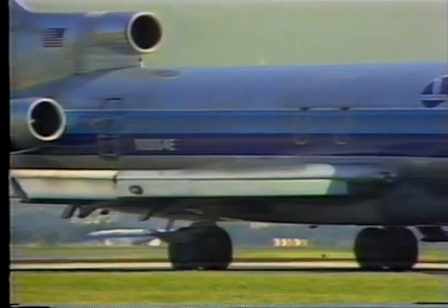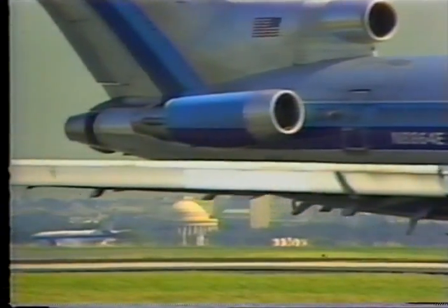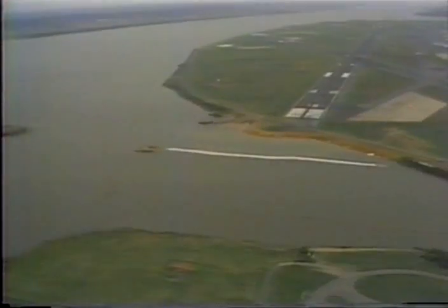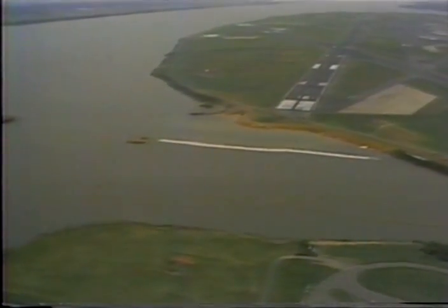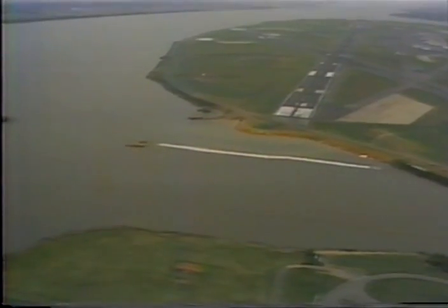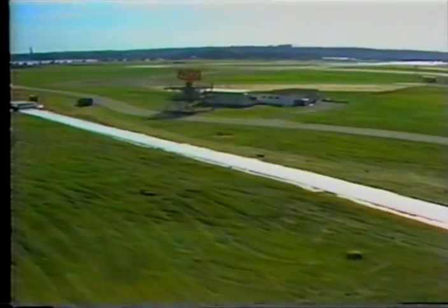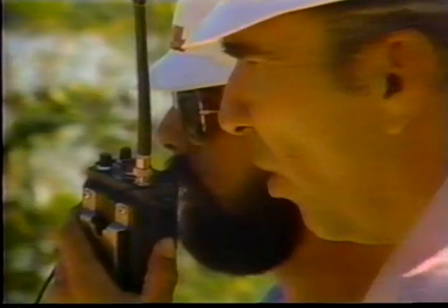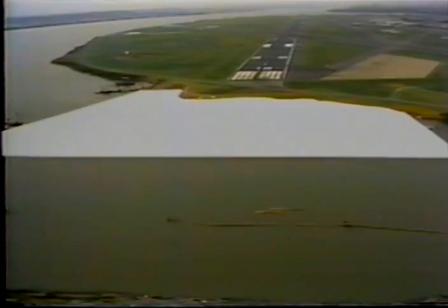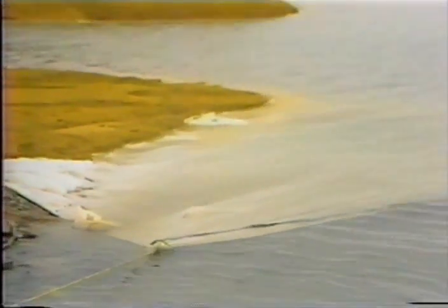In the early 1980s, a new runway extension was created for Washington's National Airport. It was constructed on an embankment section founded on soft marine deposits. For this project, a high-strength geotextile had to be specially manufactured. Once the lengths were seamed together, it covered an area the size of 3 city blocks. The accordion-folded fabric mat was towed into the river, spread out, and stretched in place over the river bottom to provide a base for the new embankment.